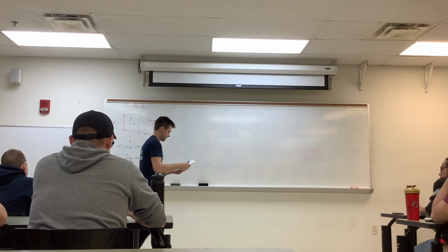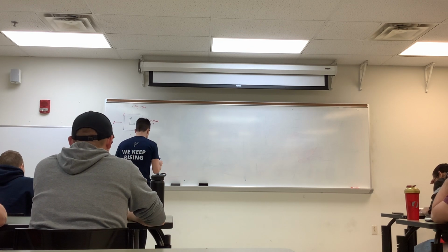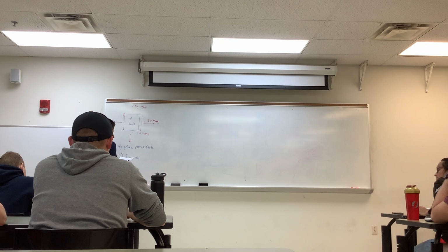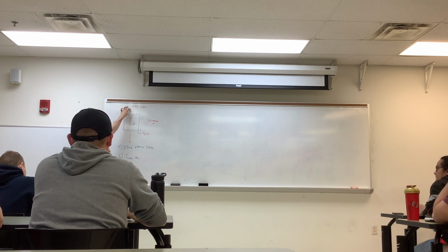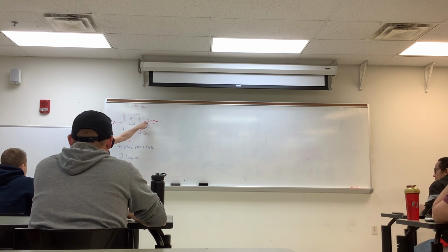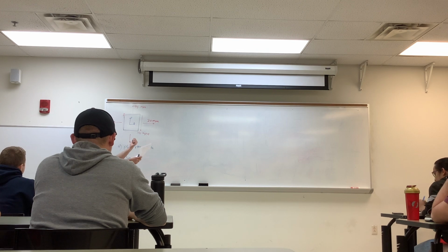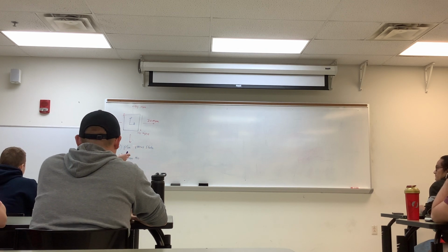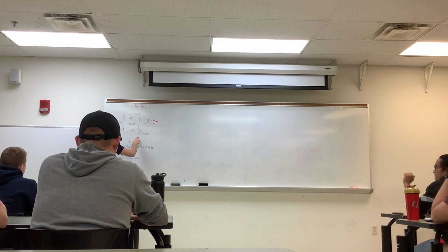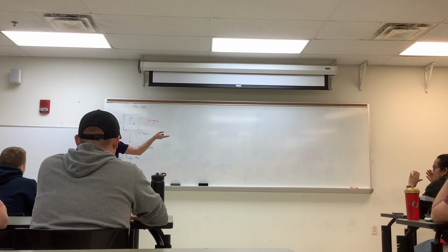So starting off with the first one, looking at this, in accordance with our axis, both 45 and 30 are positive, because there's tension, and in any kind of element we will typically consider that as positive here. So the 45 is causing tension in the y direction, the 30 is causing tension in the x direction. This shear is negative.